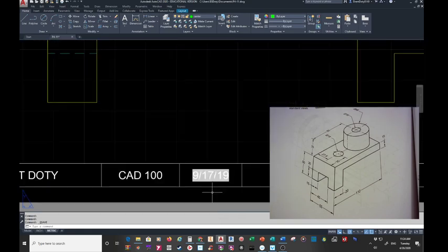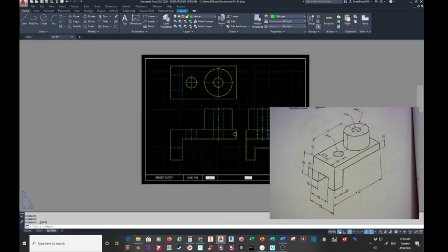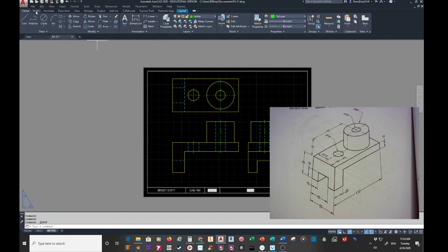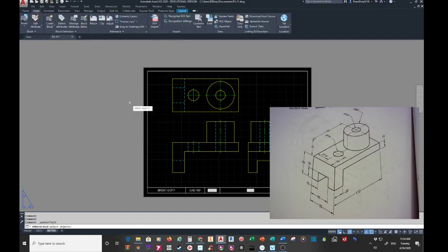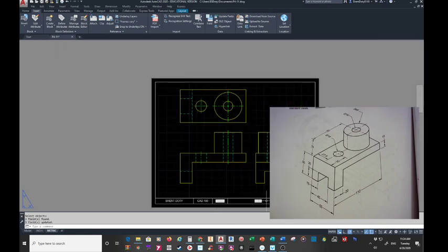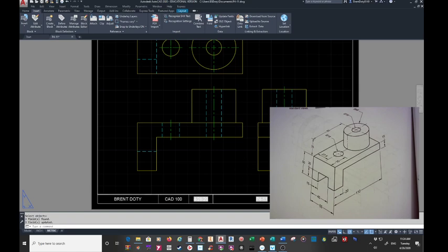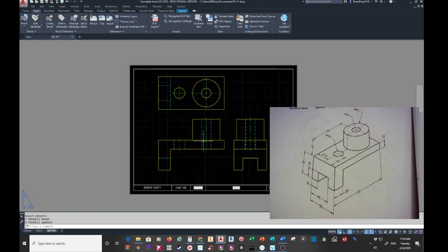Yay. This needs to be updated, so how do I update? Well, one way you can do it, or the way I do it, is go to Insert, Update Fields. Just put a window around everything. It's only going to select the fields. You hit Update or hit Enter, and then now it's set at the current date. And that'll also update this if it's not the right one. The only one that seems to automatically update is when you save it. Sometimes the dates will update. This one always updates. This one typically doesn't. Anyway, and this is my finished product.